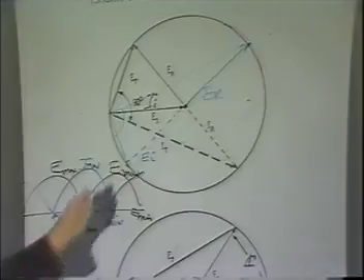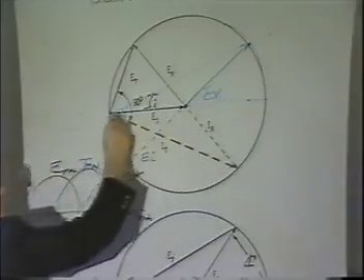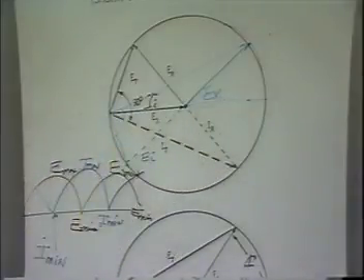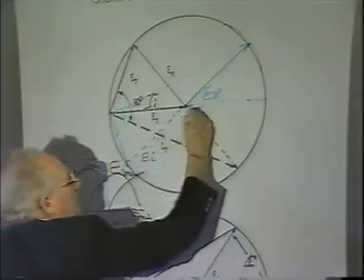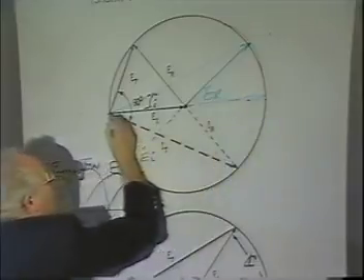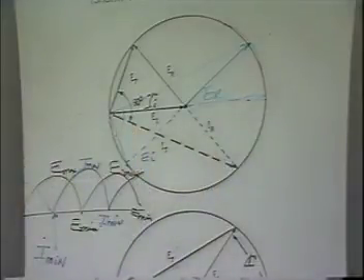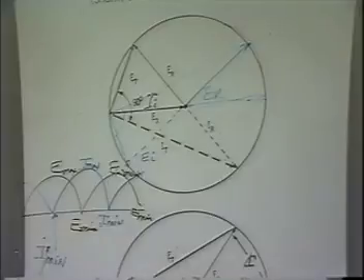Where would it be in phase? Well, if you were along this direction, right? Straight across, then there's no angle between them. But the minute you move anywhere off this line, the smallest amount, then the total voltage to the total current will always be 90 degrees. Always plus or minus 90 degrees. That's shown here, right? Always plus or minus 90 degrees.